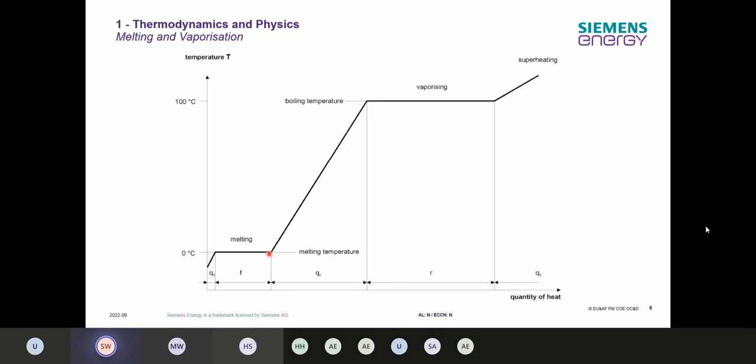The main reason for it: when water is freezing, the volume will increase. And when the volume increases and you have a certain amount of water in a pipe, let's imagine your pipe is fully filled with water, and now the temperature outside is less than 0 degrees Celsius.